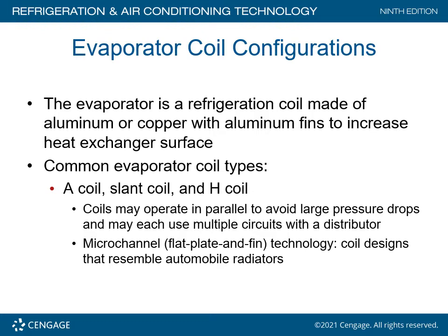It works for the most part because it increases the heat surface contact, but I will tell you this: if you ever get a leak on a microchannel coil, good luck trying to fix it. It's a real problem because the metal's thin. There are issues you have to deal with.